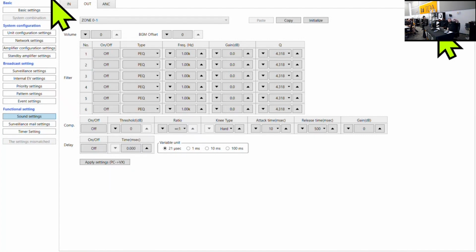So you go to communication, and you can send from PC to VX, and in some cases you want to receive the existing configuration to your software. We have instances where another maintenance team comes and they don't have a backup file, so they can connect to the system and retrieve the configuration, so they can make the changes and send back to the system.